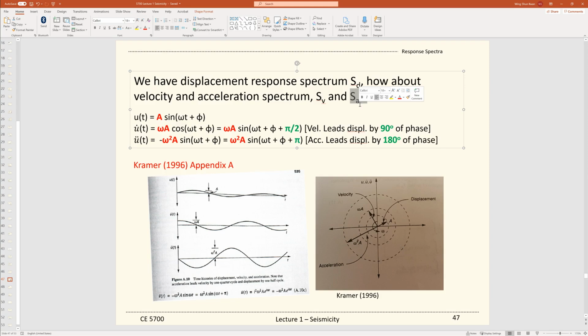So instead of a displacement response spectrum, in 99% of common design we communicate with the acceleration response spectrum. Changing from the displacement domain to the acceleration domain requires an understanding of how to change from time content to frequency content.